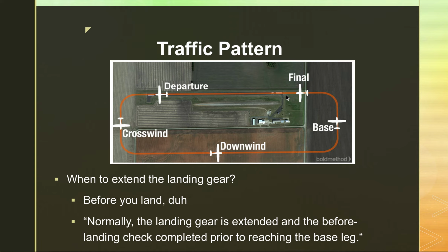And then if you have time, and when I'm on short final, I'll do like one more final gear check. All right, I had a flight instructor in the past that would mess with you on short final and like raise the gear or pop off a circuit breaker and stuff to see if you caught it before you landed, which I would not recommend.